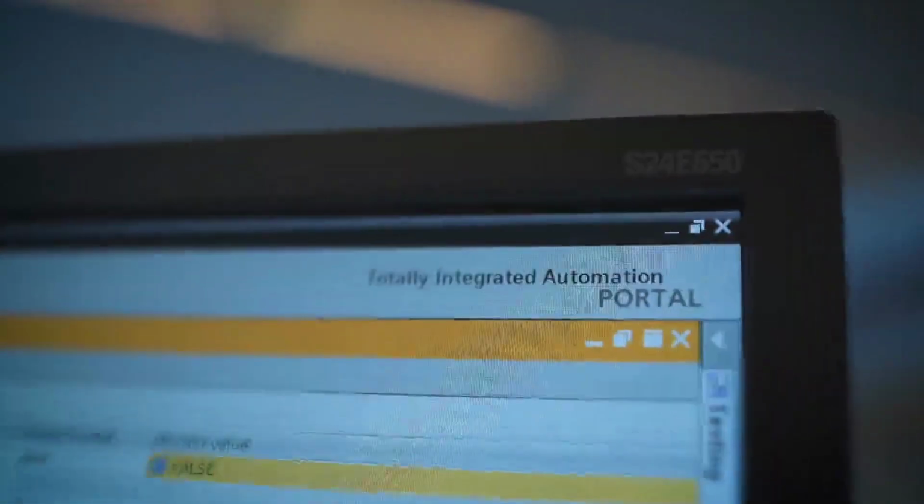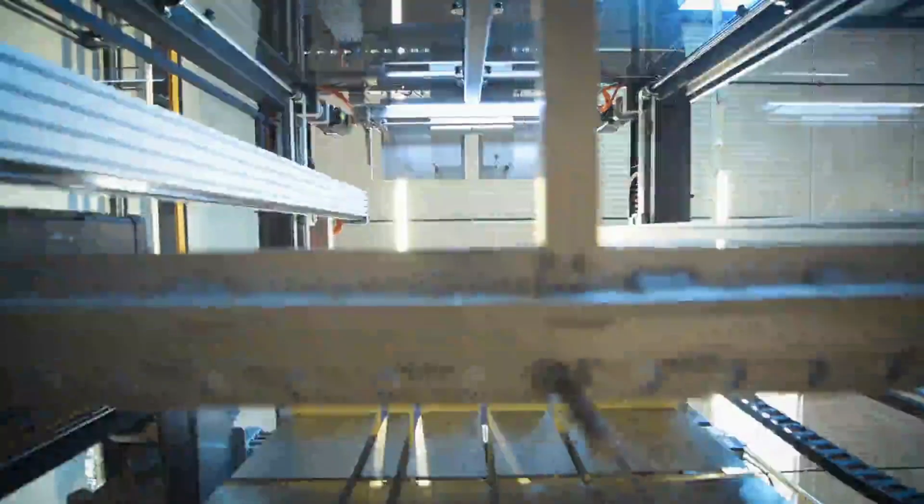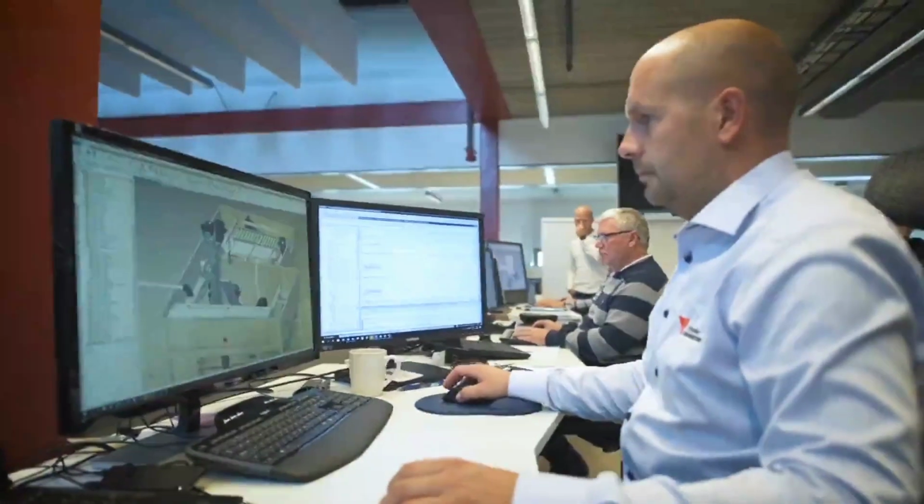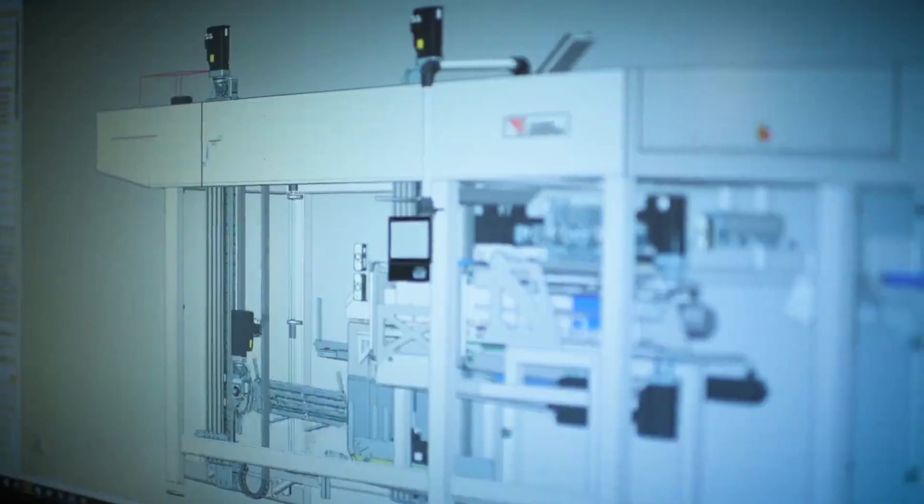Virtual commissioning for us means that we can actually test a lot of things in a virtual environment before we need to build the hardware. We realized virtual commissioning with the NX tool and the Mechatronic Concept Designer and the PLC SIM Advanced together with the TIA Portal. The main advantage we received on this machine with virtual commissioning is especially on the kinematics setup of this machine. Because of having two kinematic systems work in one shared space, we could test out the complete system in a virtual environment. And of course we had some virtual crashes, which saved us a lot of money.